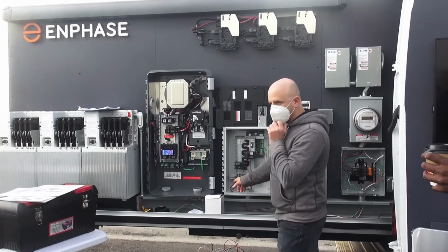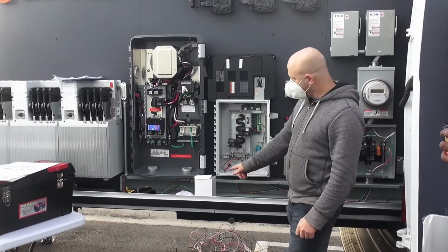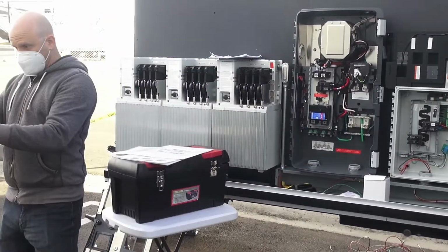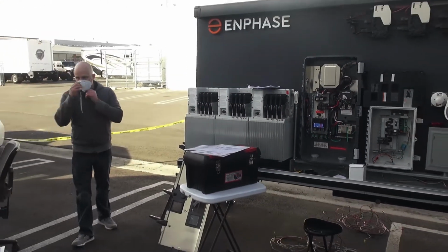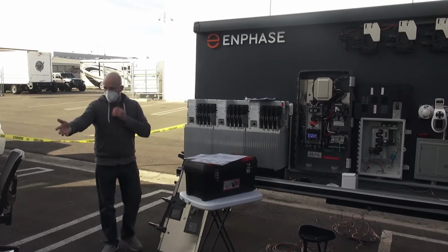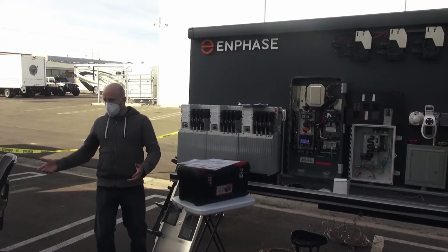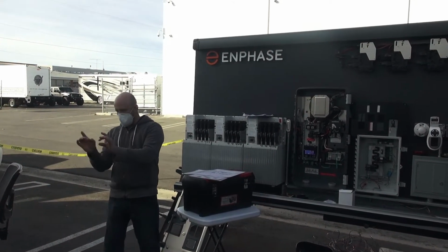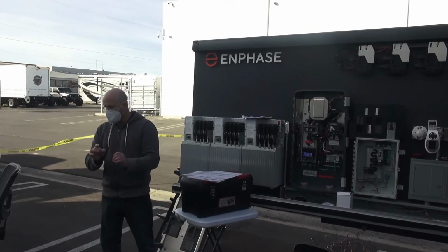If we start here, that's the production CT, right? So that's how we measure the power. How do I measure what the homeowner uses? You just said it. With the consumption CT. Where do those go? Homeowner uses consumption, on the grid side. The consumption CTs, where do I install those? Consumption, grid, from the main panel.